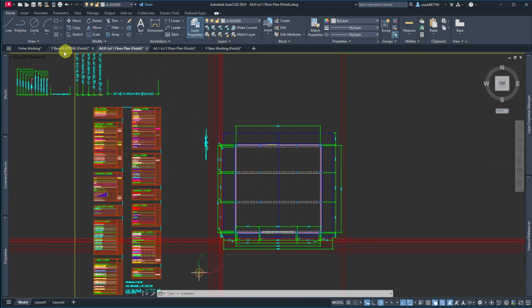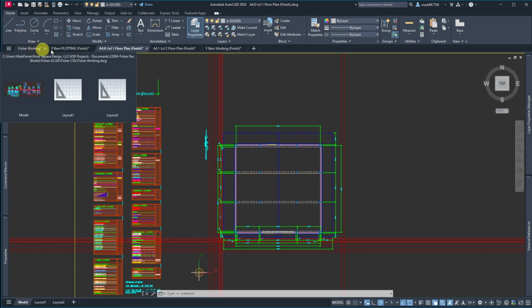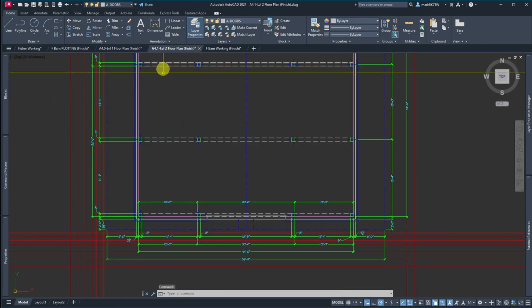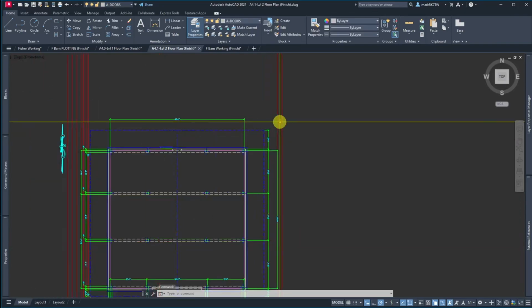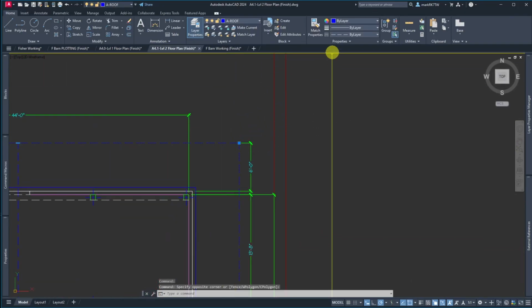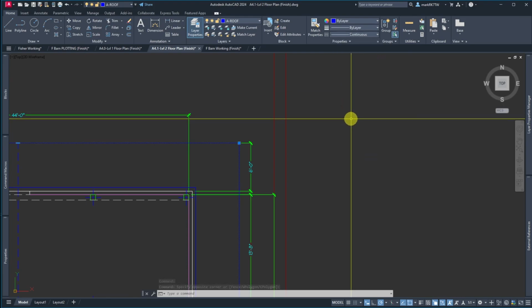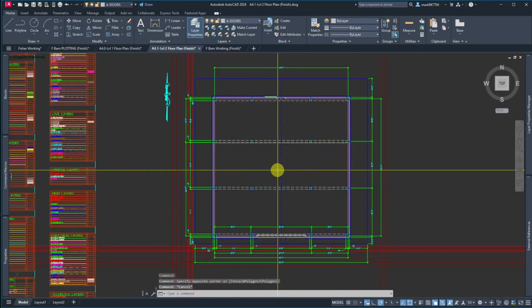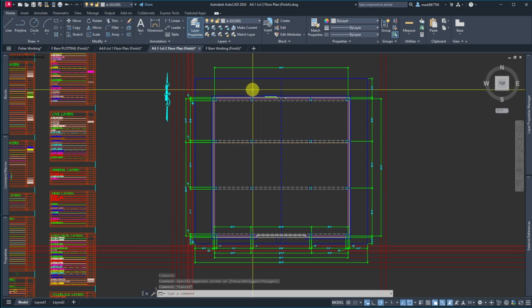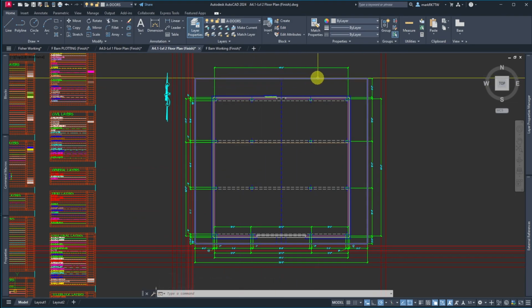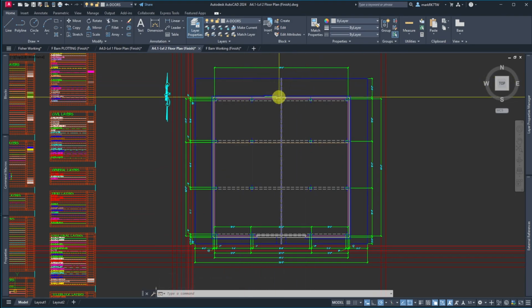We'll be able to see that in level 2. We'll see the secondary roof, and this roof will want to be a solid line, so we'll turn it to continuous. And if we extend out the back, we'll have to explode it and then make it dash through here so that the roof that comes through here is covering it.